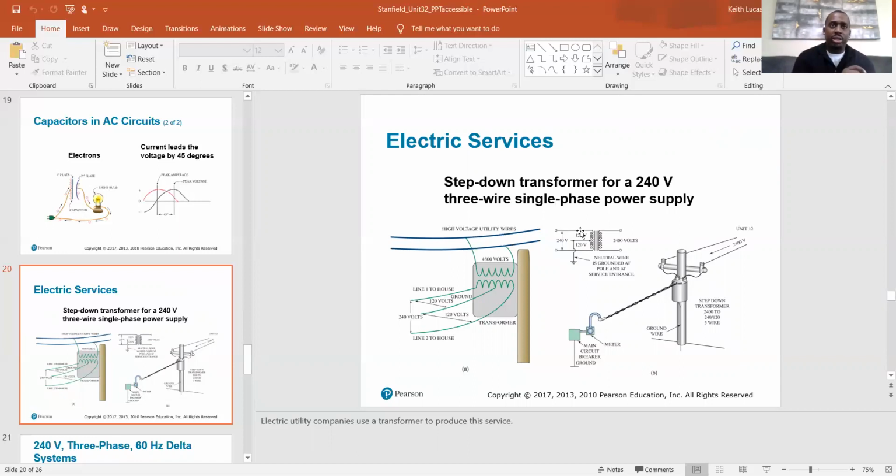When you call for cooling, certain contacts need to be closed, certain things need to be open. We need to energize certain things. When you call for heat, you need to energize different things. The circuit board on the thermostat is doing all that. It's communicating, saying, okay, we need the heat, so we're gonna need our induced draft motor, we're gonna need our high surface igniter, we're gonna need our blower motor, we're gonna need our gas valve. We need to power those things. So the thermostat is what's communicating with the system and sending power to those specific items.